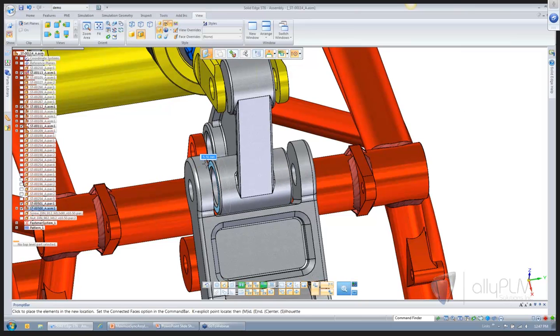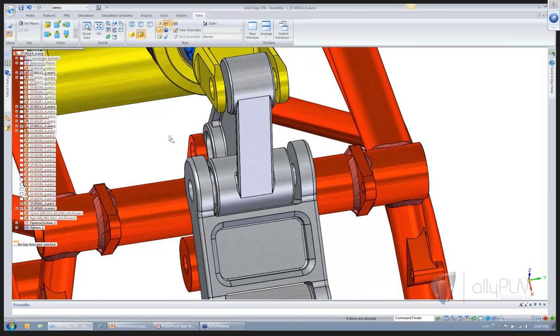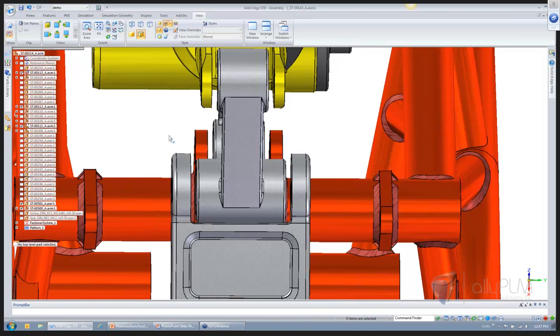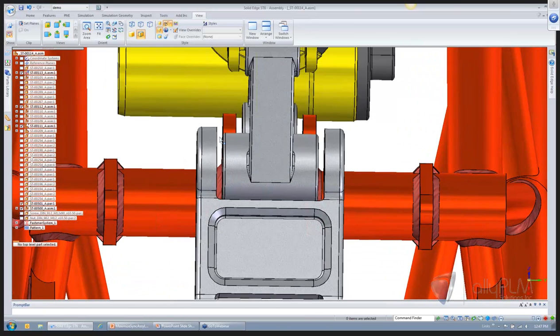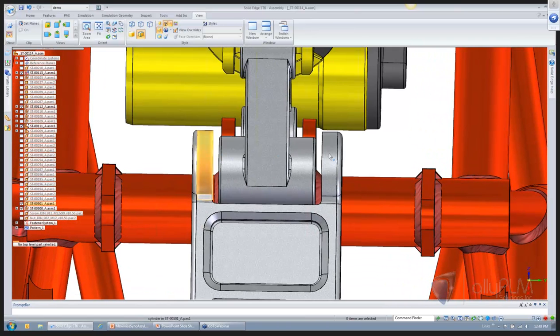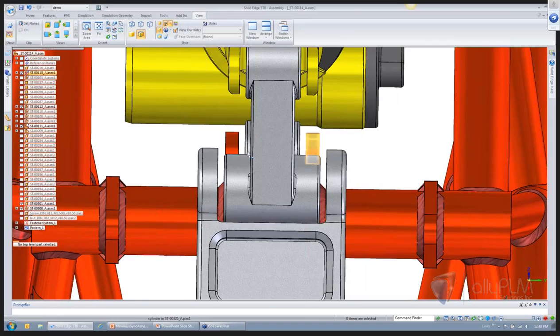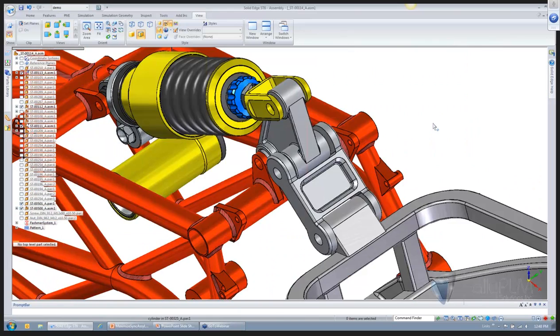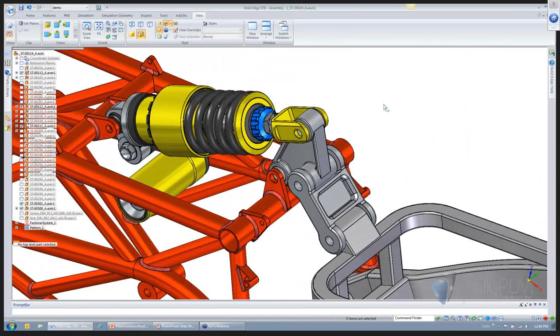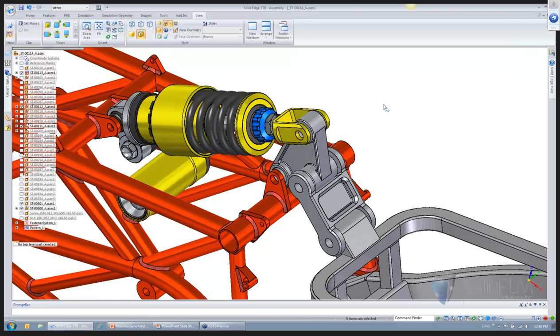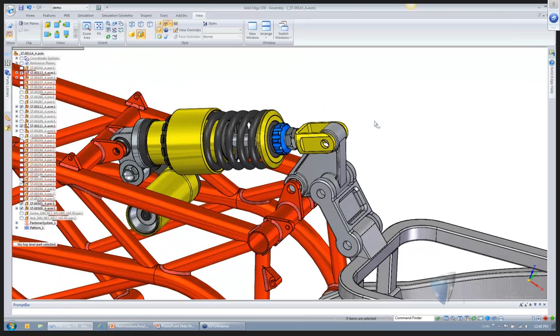And now when I begin to make this edit and then pick up on this key point, you see that I made a part level edit at the assembly, but I honored the design intent that said, hey, I'll need 3 millimeters equally on both sides of this part. So here we are doing part level design at the assembly without needing to stop our workflow, go in place activate, make an edit to the part, come back, close and return, and see what happened to our assembly.